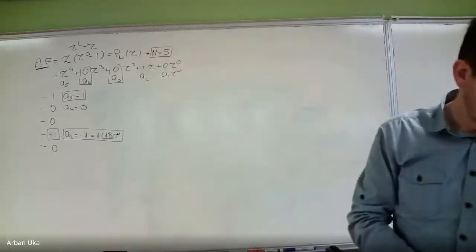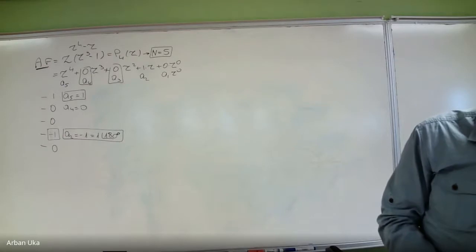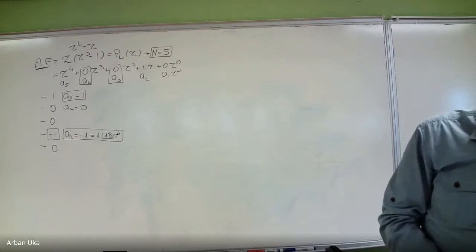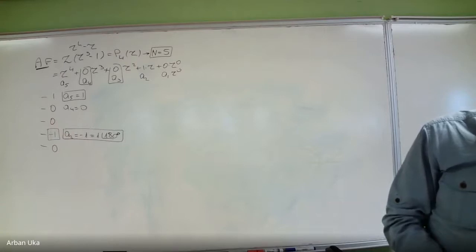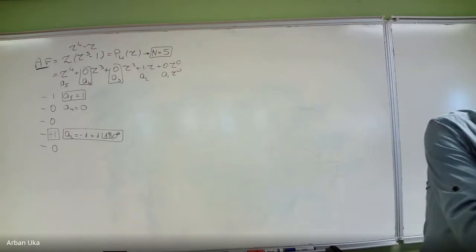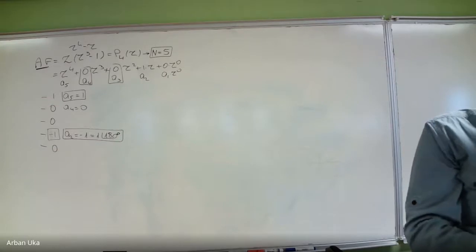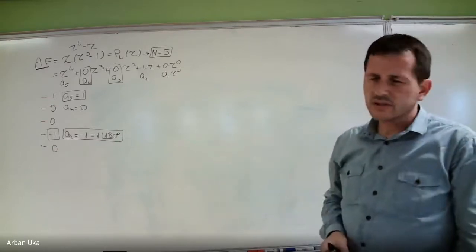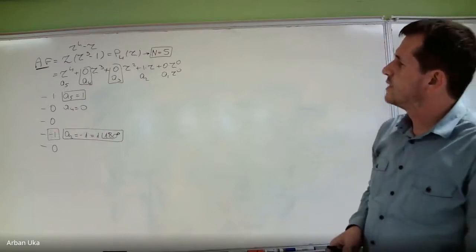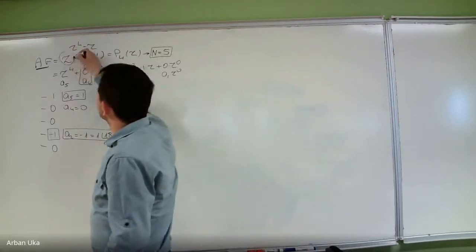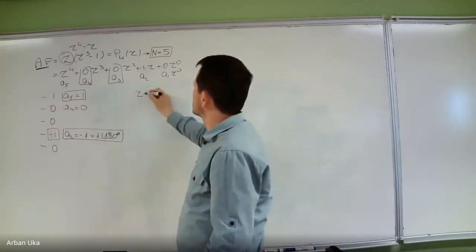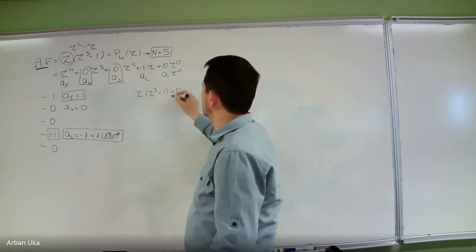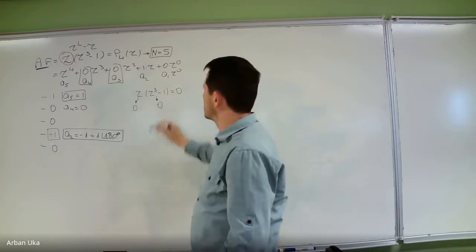So if this is the case for this specific antenna array component, we found what these elements are, and now what we can try to determine is also where we are going to observe the nulls. Okay, so this is also an important factor. Now, in order to determine the nulls, we should find where this array factor is equal to 0. In fact, we can say that in order to find the zeros, this is z times z to the power 3 minus 1, this is 0. Now, either this one is 0 or this one is 0.